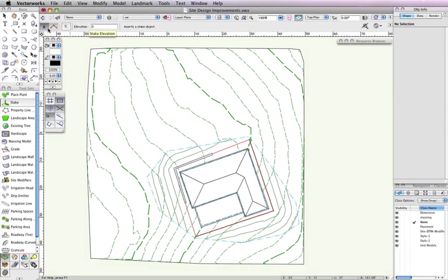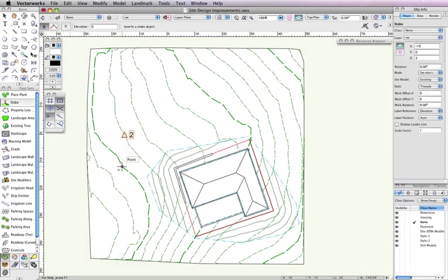This first mode in the toolbar will insert stake objects one at a time. The second mode places a series of stakes based on a path from your mouse clicks. This mode gives you the ability to use the floating data bar to set stakes based on the previous stake points. Once placed, these stake objects are not associated in any way and can still be modified individually.